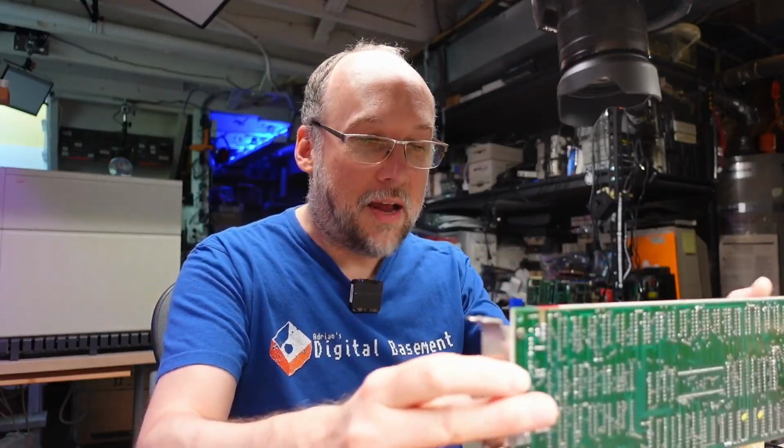So what IBM decided to do is use a feature of the 6845 CRTC to have an output that actually disables the entire video image while the scrolling is going on. So instead of seeing snow, you're just going to see a black image. That flicker that you get during scrolling is very obvious when you use the CGA card, and that was the design decision that IBM made, and I guess they felt that that was a better compromise than seeing the snow.